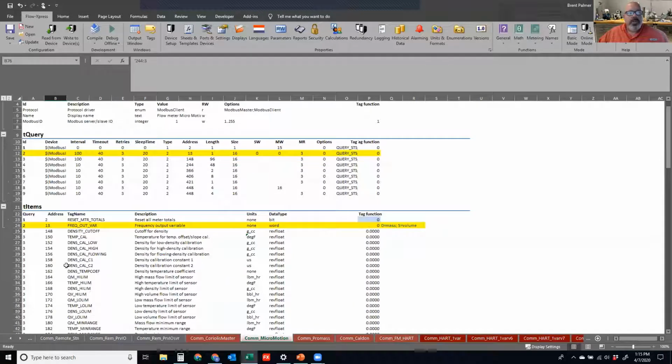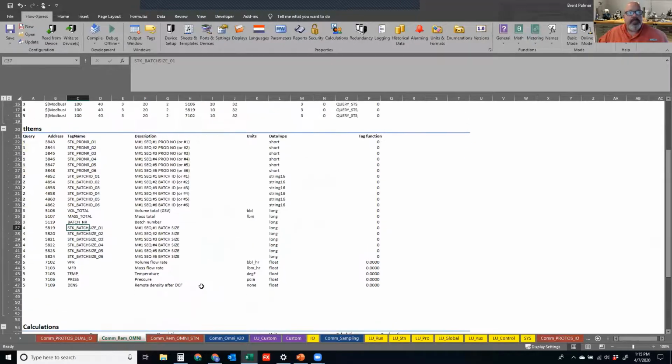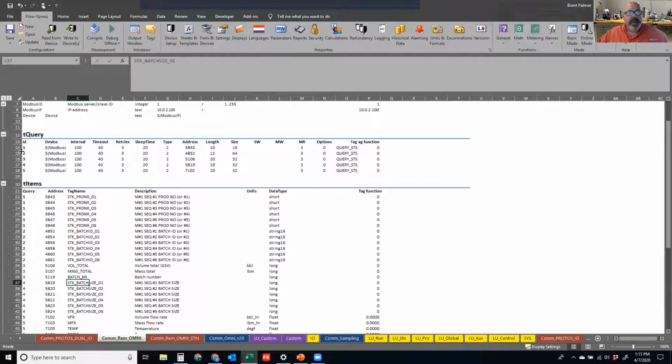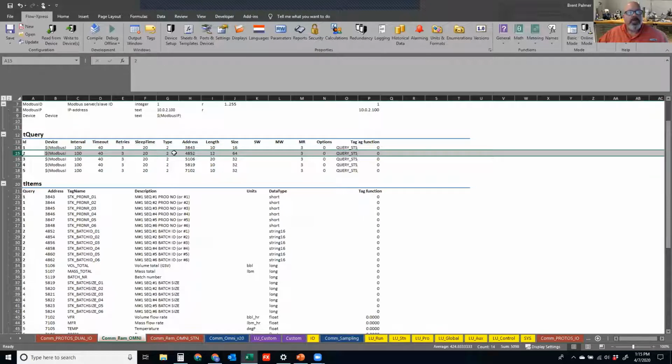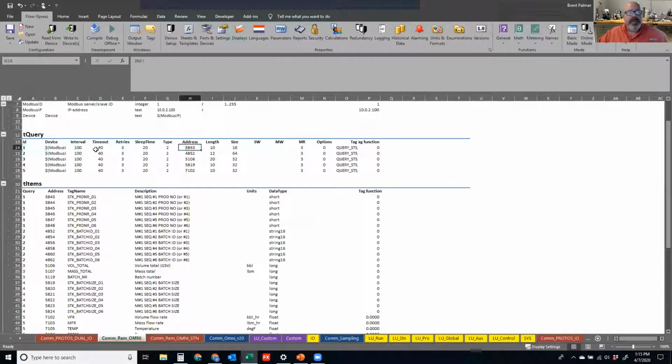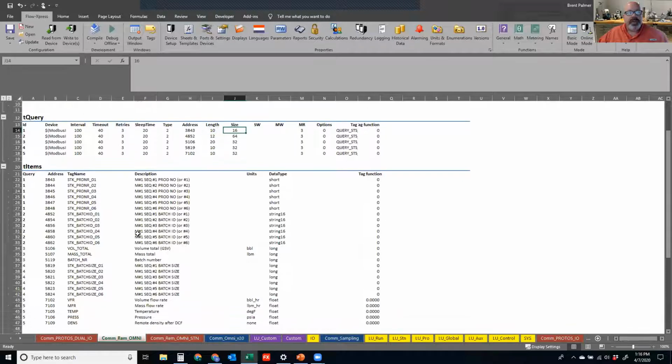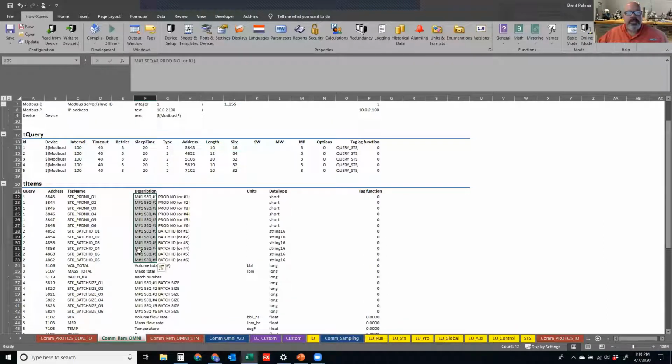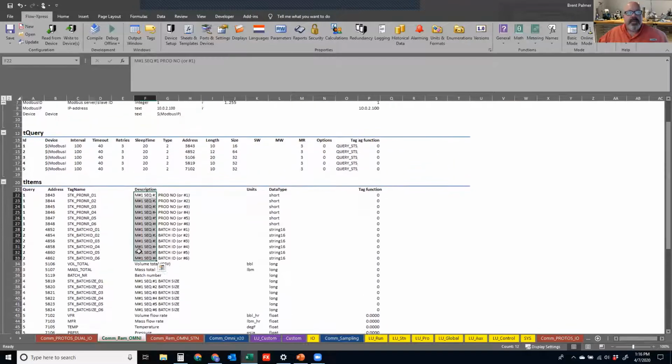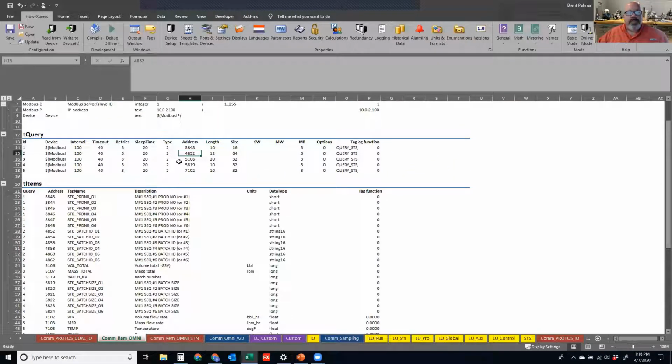So if I wanted to create and poll something, let's use an Omni. If I want to poll an Omni for information, I set up my different queries, 1, 2, 3, 4, depending on how the breakdown of addresses. So what I'm saying again in this one is, hey, every 100 milliseconds, poll the Omni for address 3843. I want 10 registers brought back, and they're going to be 16-bit in size. And I know that inside the Omni, that's the information that I'll be getting back. And then I want you to poll 4852 for 12, and then 5106.